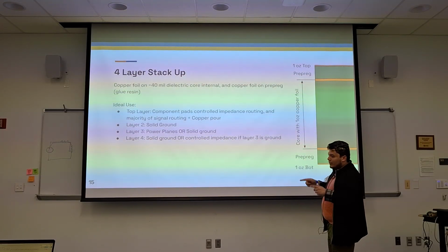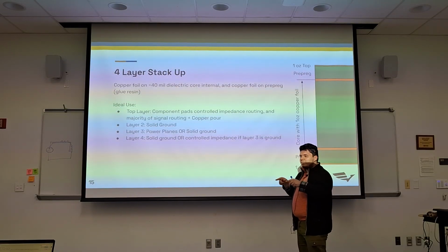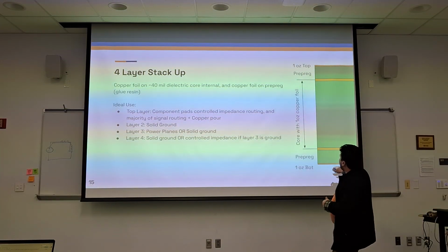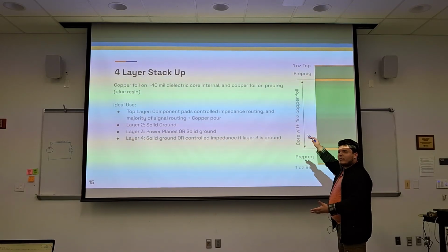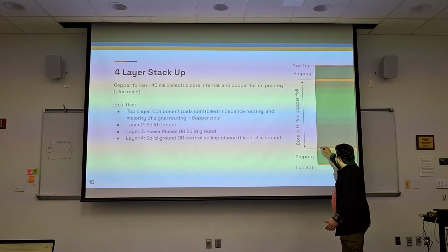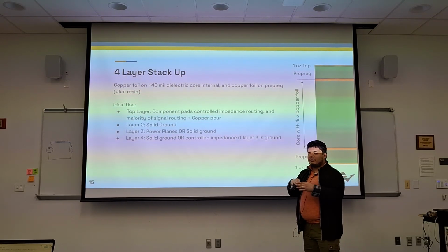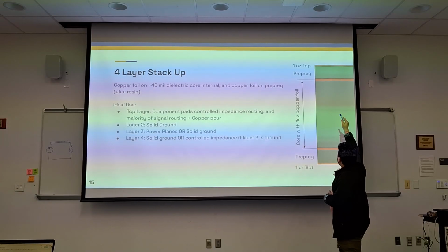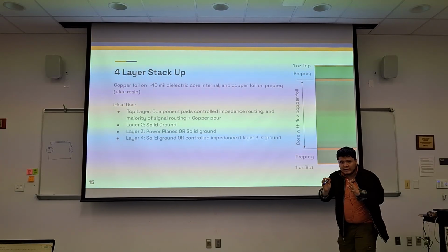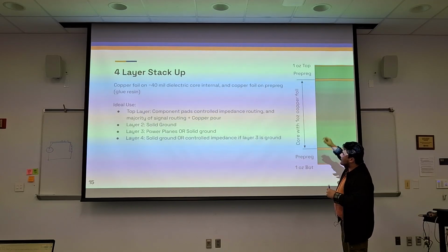Because when you increase the loop, you add inductance into the system. By making this loop bigger, or if we keep a big loop, we add a lot of inductance. And by shortening this loop, we reduce the inductance, we reduce potential ringing and signal degradation, right? That would be a good use case of getting a nice reference plane, nice and close.